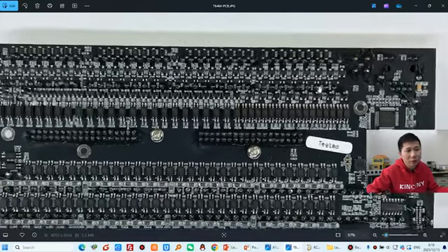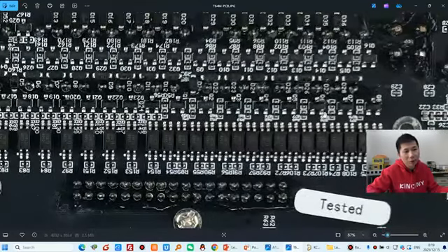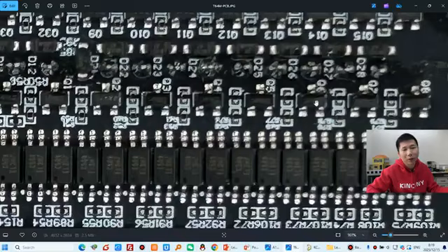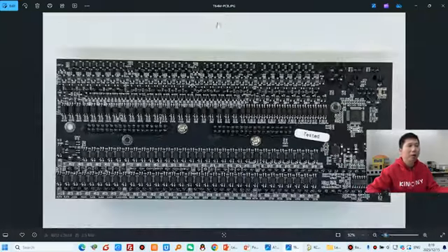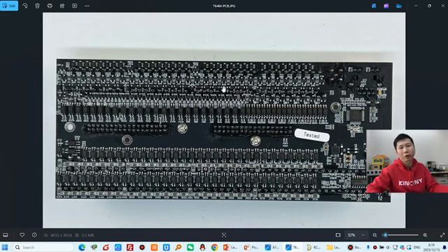Those boards use this small MOSFET. You can see the MOSFET size is smaller. So the max is 4 ampere, because the 64 channel is a very large number of channels. So we want this board to become smaller, which will save space in your power distribution box.